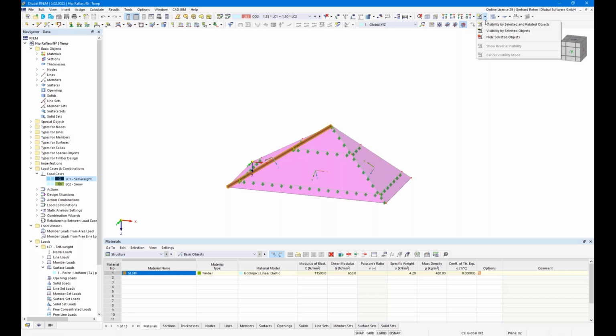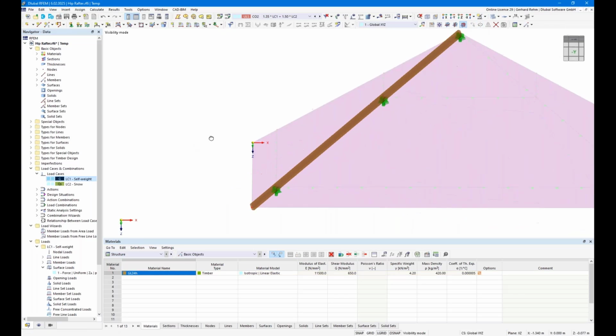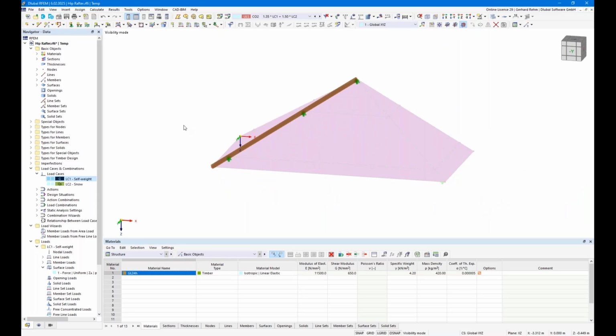Okay, so far for the load combination, and let's focus actually only on this hip rafter. So I will create a visibility, and I will define some parameters for the design. So we finished with the loading. So now we can focus on the design. So here I have 3 separate members. I could also model this as 1 member and use intermediate nodes.